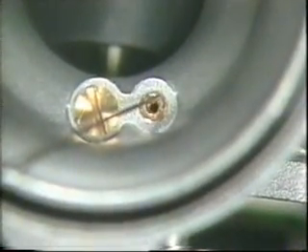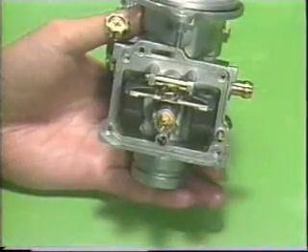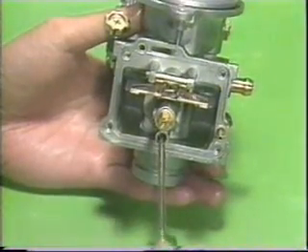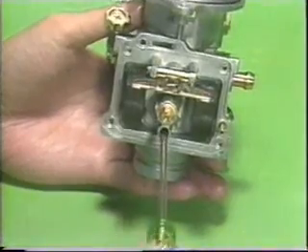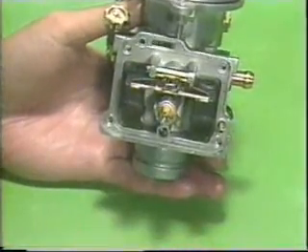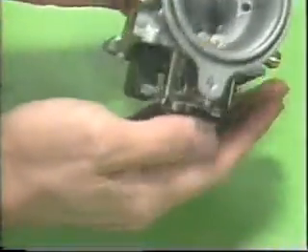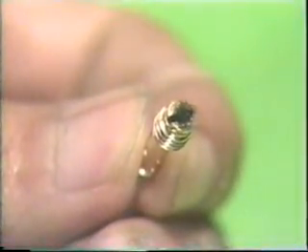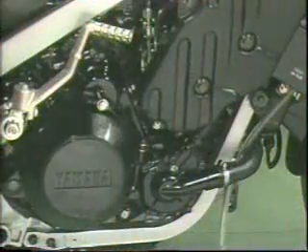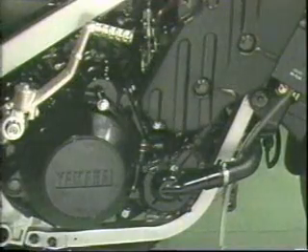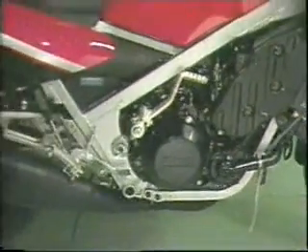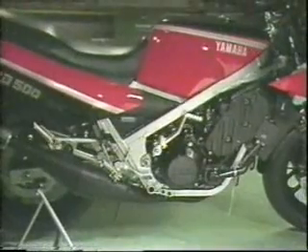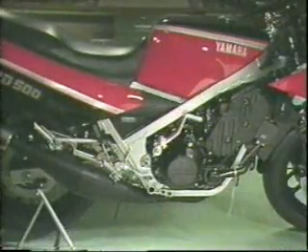Is the pilot air jet clogged? The answer is no. It looks okay. Is the pilot jet clogged then? Uh-oh, yes, it is clogged. This is what is causing the trouble. The foreign particle is now removed. Let's put the parts together and check the result at idle speed. It's good. It's running properly now. As we just saw on the screen, problems associated